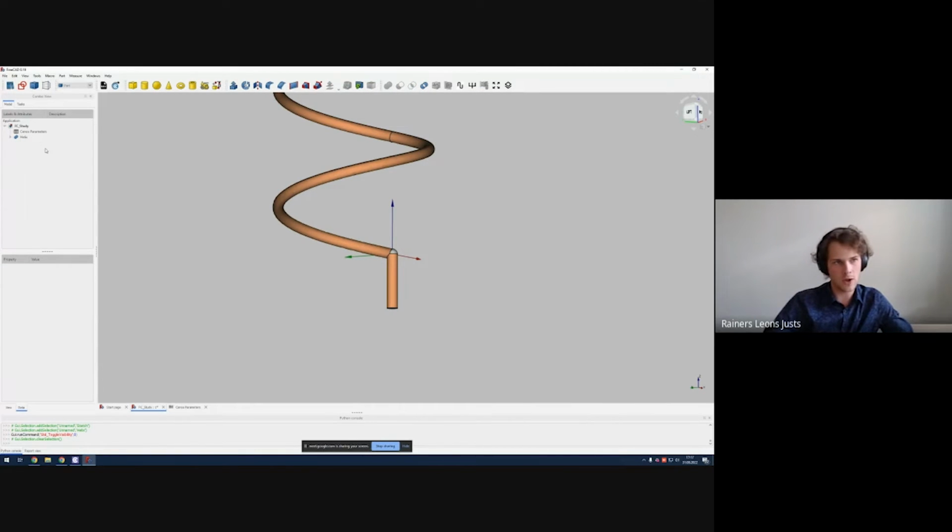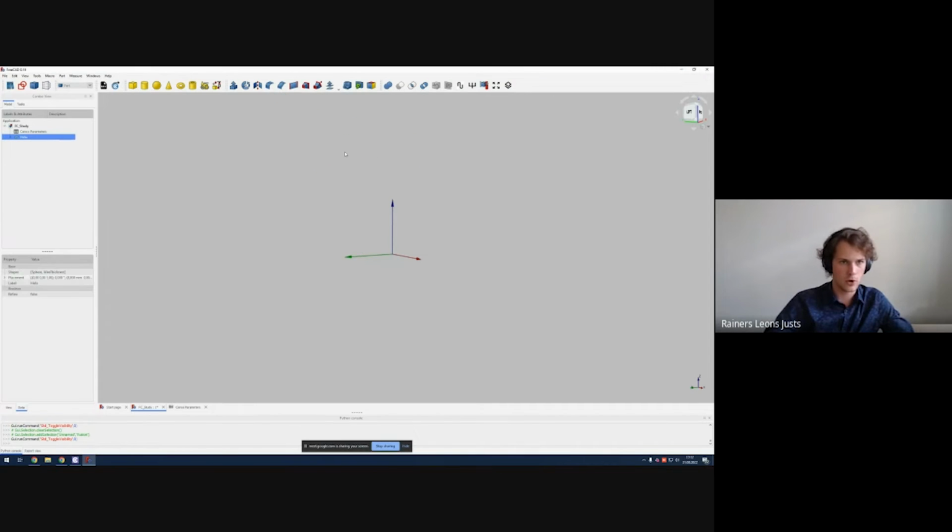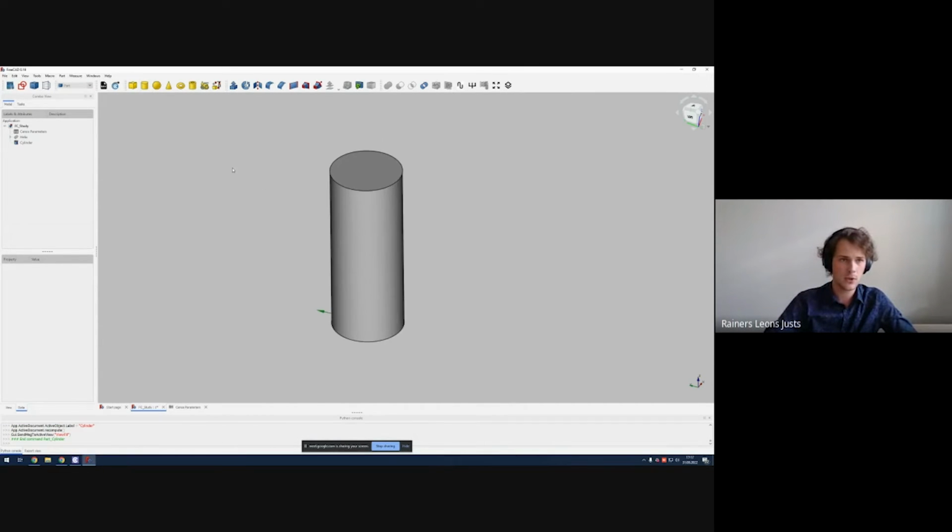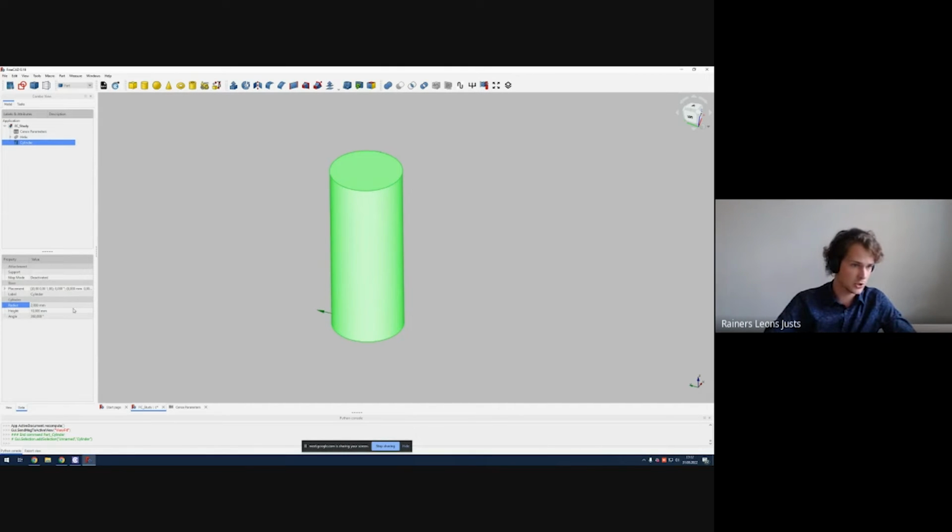To create the ground plane, we're actually going to be using 2 tools. First off, for the general ground plane disk, we're going to be using a cylinder. And we're going to need another cylinder afterwards to cut out the hole for the inner dielectric and the dielectric of the coax and the inner conductor. So let's change the parameters to fit our needs.